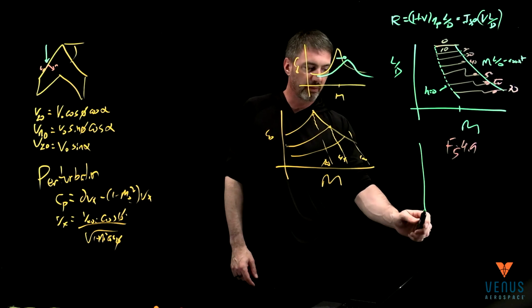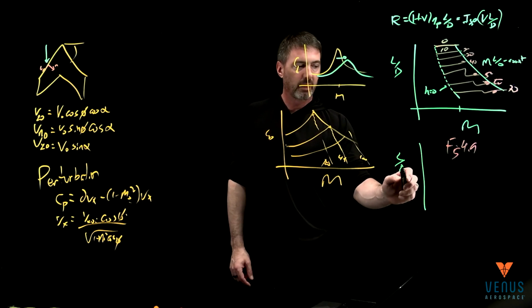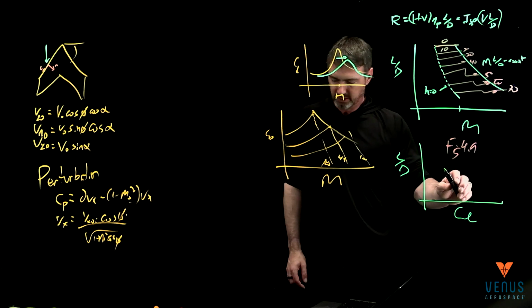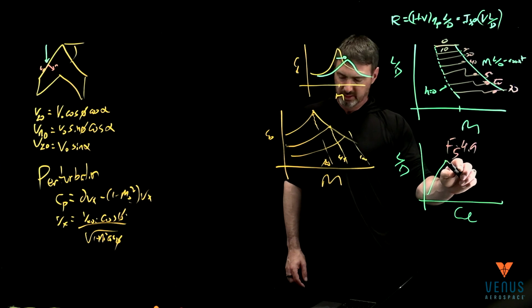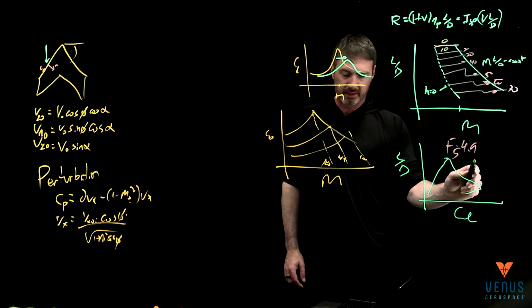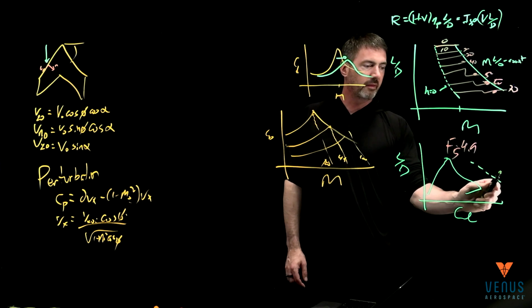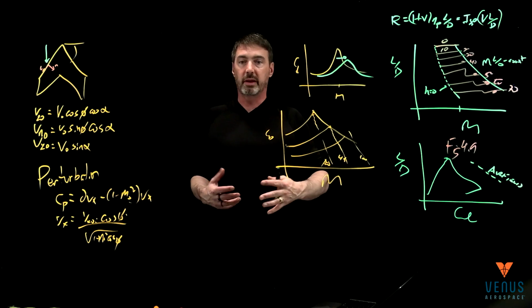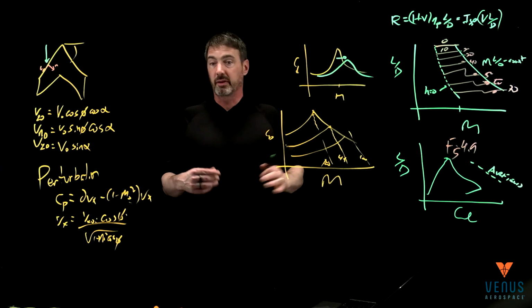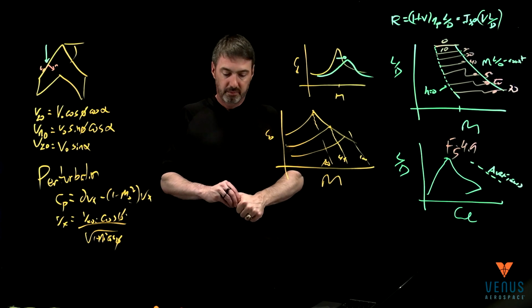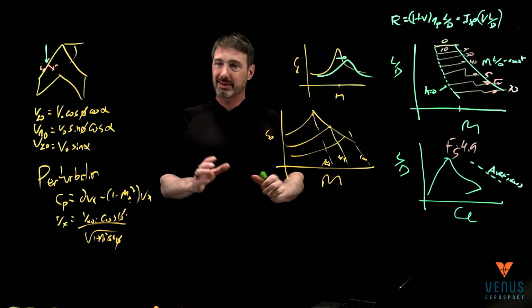And in fact, if you take a look at L over D, and this is versus lift coefficient, I know I made it crowded, but you end up with something that looks like that. And then this is where you need to be for the airfield. So that says you need some other high lift device to help out, so this kind of aircraft still performs well on an airfield. So that's sweep.